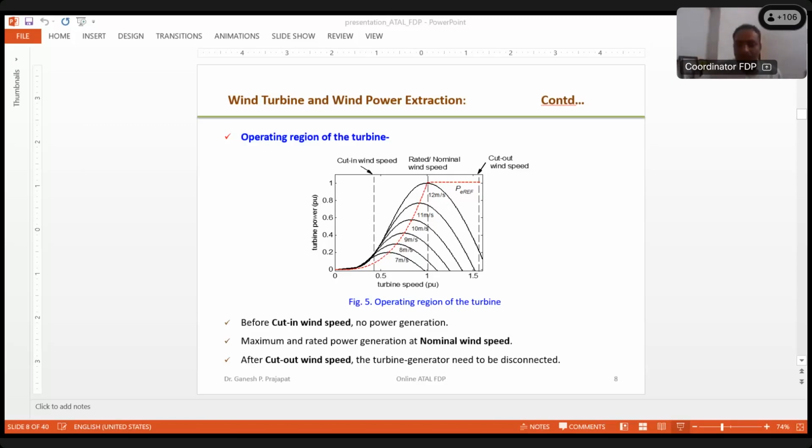Why? Because here the power generated by the generator, the total power, flows through the converters, since these converters have to handle all the power being generated by the generator. In that case, the size of the converters will be very big, because the size of any electrical equipment depends on its handling capacity of voltage and current.